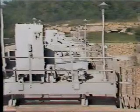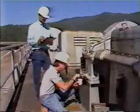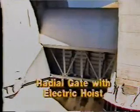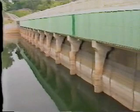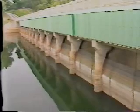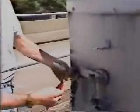Now that we've reviewed mechanical equipment and systems and common deficiencies associated with them, let's look at typical inspection procedures for gates and their operating systems. The first example is a radial gate with an electric motor-driven hoist. A radial gate can be used to retain water above the control section and to release and regulate water flow. If you are inspecting a gate with water behind it, make sure that the gate has been immobilized. Use red tag and lockout procedures to ensure that the gate won't accidentally be moved during the visual inspection.